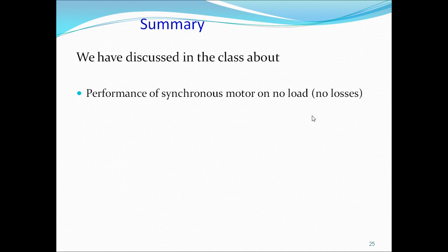The voltage across armature is V minus EB. As both are equal, the resultant voltage across armature is zero. When the voltage is zero, armature current is also zero. Hence, the motor is not going to take any external input from the supply.